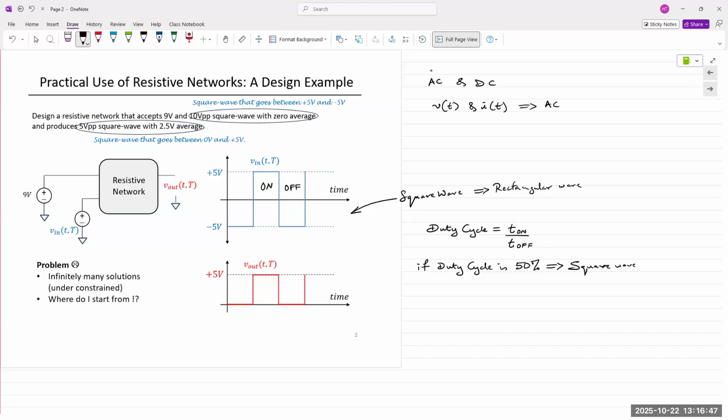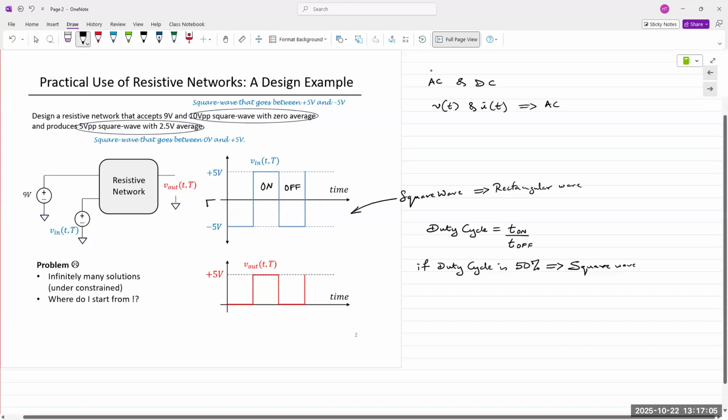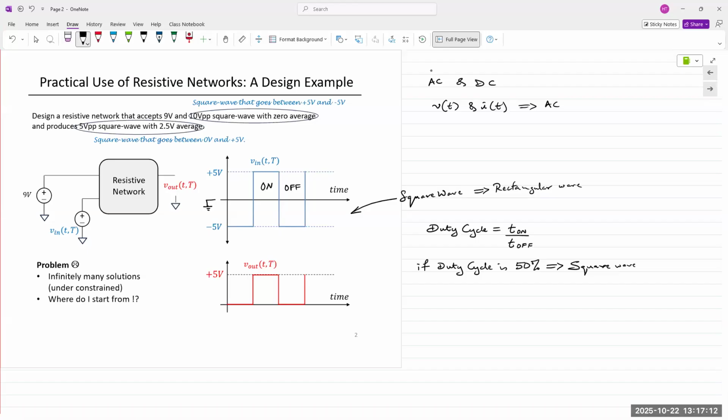On an oscilloscope, when you look at this, have you ever noticed that on the left side of the screen, there is a ground symbol? If you haven't, then the next time you're in the lab and you're using an oscilloscope, take a look. You will see this kind of symbol, either a triangle or 3 lines arranged in a triangle. It's very tiny. It's on the left side. What it is showing you is the reference level for that waveform.